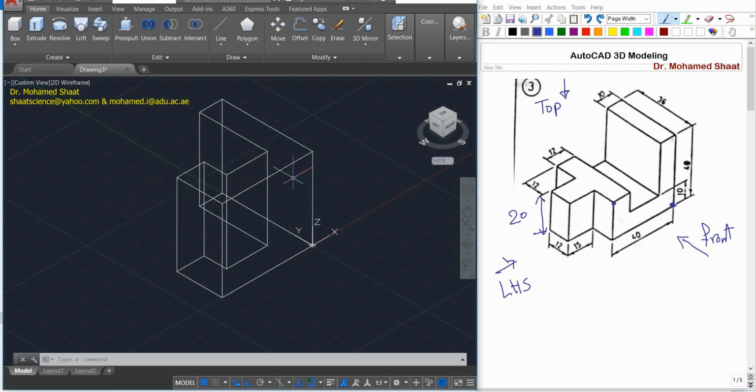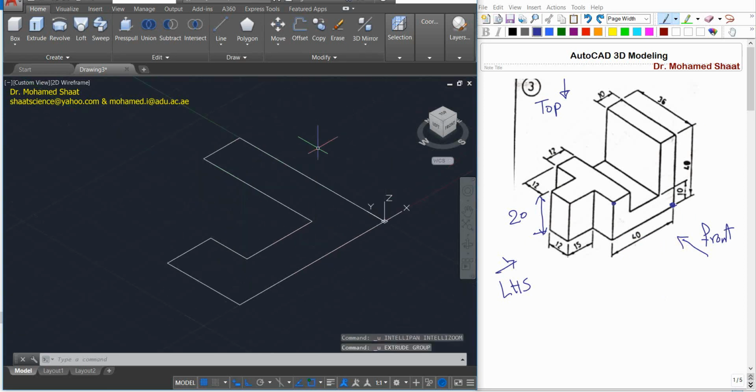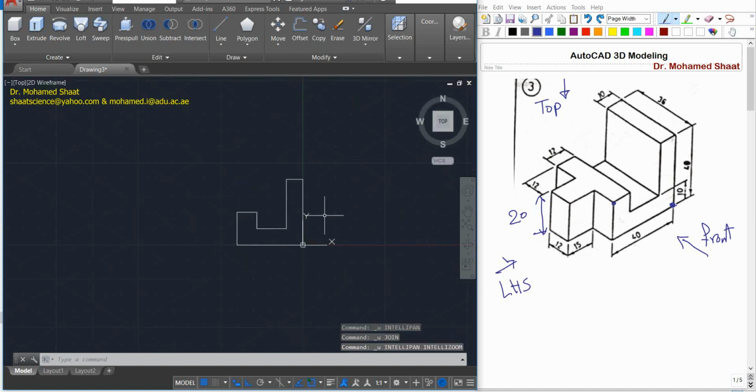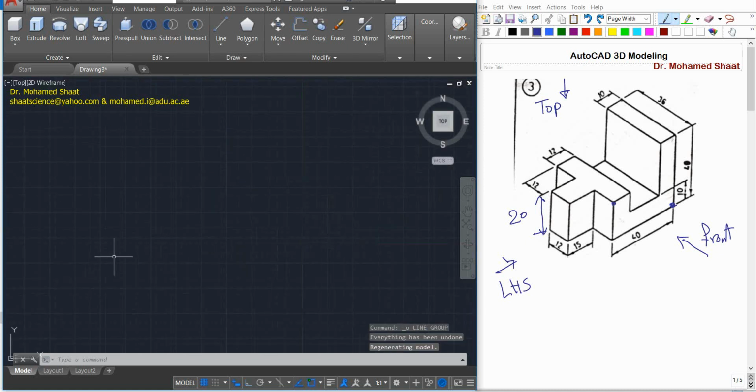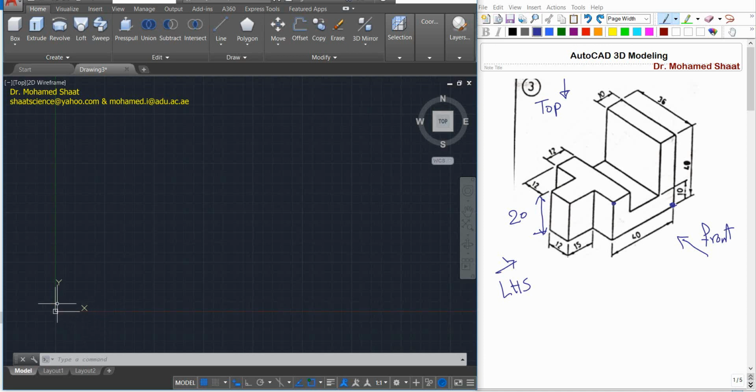So this is what I'm gonna do. I'm just gonna start from scratch, because I do have this thing differently represented over a different plane. And as you can see, by default, as we mentioned, AutoCAD draws over the top view, which is the XY plane as already given here, and this small square box indicates that this is the plane over which you are allowed to draw. Any drawing will be seen over this plane. Make sense?